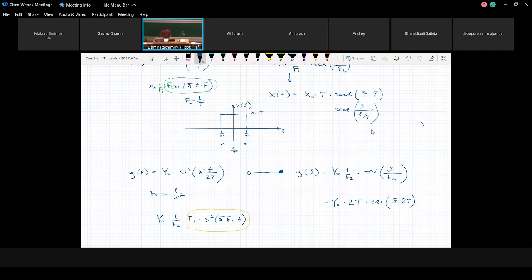So next part, we go to part B. Now we do the following: we assume that signal x of t and y of t are mixed into an intermediate frequency range first, and we have this expression for how we do this. And the whole idea for this discussion is that you have a transmitter and you use a so-called heterodyne architecture for your transmitter. And then, of course, a similar architecture for the receiver. How do you do this? You divide all these conversion steps into two parts.